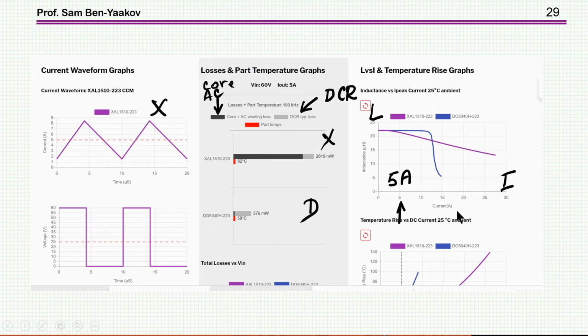Now, it shows here the information about saturation of the inductance. We see that one, which is the D, okay, is saturating very quickly, while the X is saturating slowly. This is the iron powder here, which is kind of typical. But then here, there is something which is very strange, which I cannot explain.